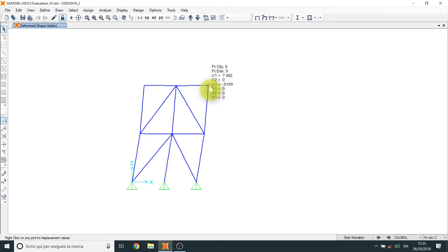That means, okay, this is not a real case, but in real life maybe you have a displacement limit, because here there is something. Maybe with 3 you are okay, but your real displacement is 7, and maybe you can have problems of collision or others. Also pay attention: when you have great displacement, you have great flexibility and great second order effects, so great bending moment and so on in your frame.